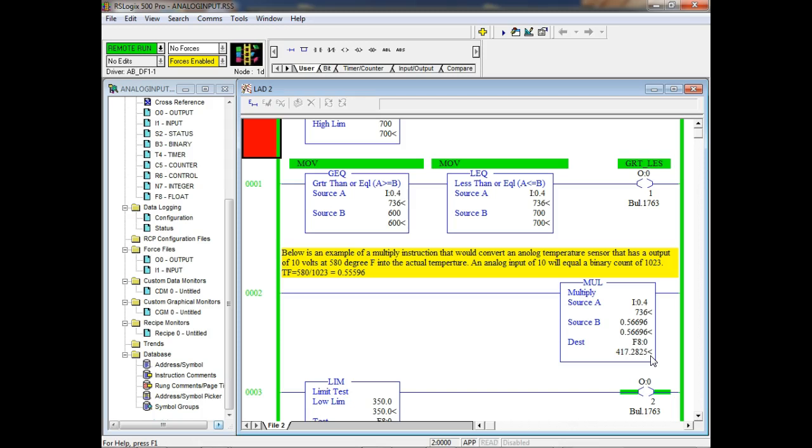So this is what you would have to do, right? You understand, if you wanted to use the information, I understand degrees, I don't understand what 1024 is, right? I would like it to be converted over to some unit that I understand. So what we do is we just figure out a transfer function. So whatever I'm getting, I would take 10 volts, I'm sorry, 10 volts would represent whatever this was, right?